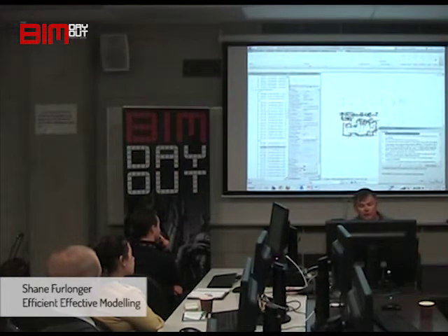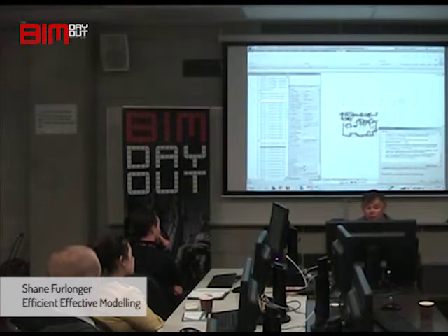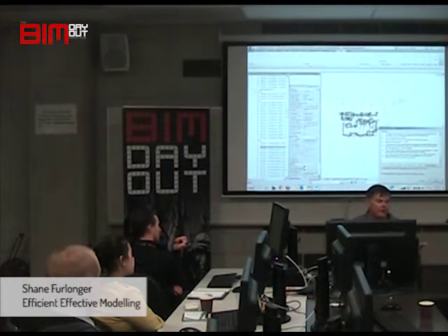So use that little box that appears in the bottom right-hand corner and don't ignore it, because it will save you a lot of time later. Because if you get that warning where it says that the wall's slightly off axis, and then you go and align a floor and go and align a ceiling, they're by sketch generally, is the way most people create them.